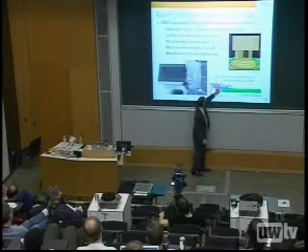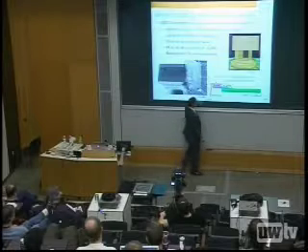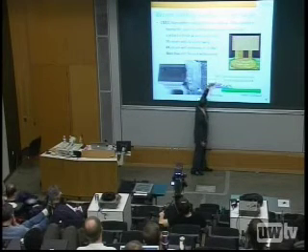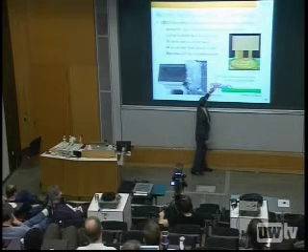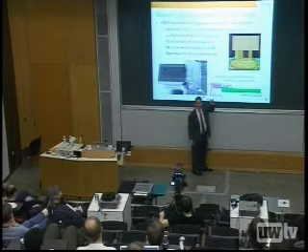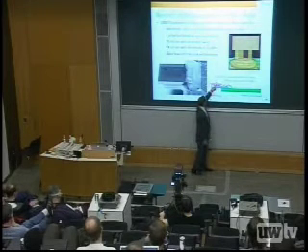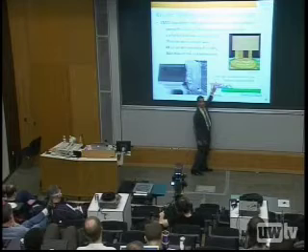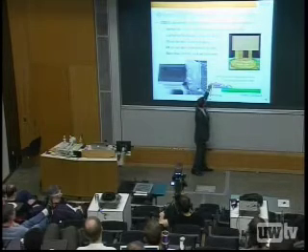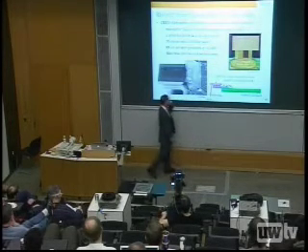So here's our chip. This blue one is this chip right here. It's mounted on a PCB. On top of that, we drop an optics chip. We micro bump it. This is solder at about a 20 micron pitch, very fine pitch solder. So we can drive the modulator and the receiver devices on the optics chip, and fiber can bring light in and out of it. And we've talked about this at a couple of conferences.